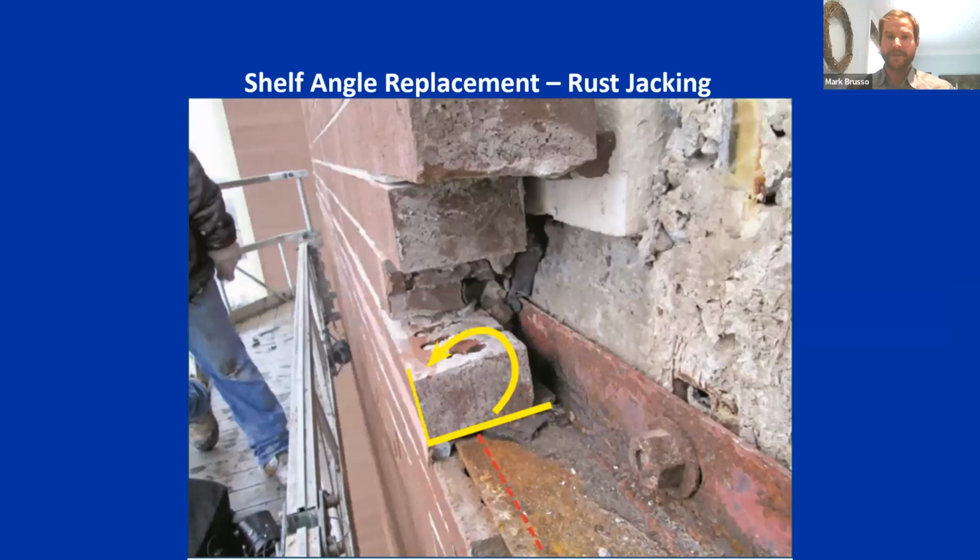So it's no secret that the through wall can be built incorrectly and it can incur moisture and damage and break down over time. This is a restoration project I was involved with, and this is an example of a shelf angle that has corroded over a period of time. When the shelf angle corrodes, steel will expand as it begins to separate and layers form, almost like how water expands when it turns to ice. Rust will expand and do what is called rust jacking, forcing brick off of the shelf angle and trying to project it off of that shelf angle.